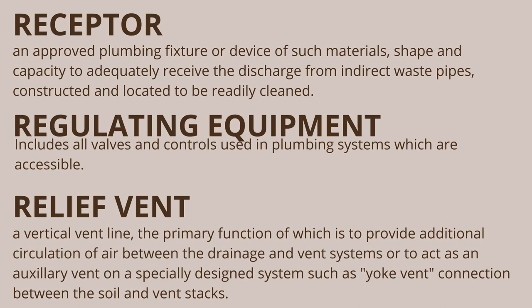Relief vent. A vertical vent line, the primary function of which is to provide additional circulation of air between the drainage and vent systems or to act as an auxiliary vent on a specially designed system such as yoke vent connection between the soil and vent stacks.